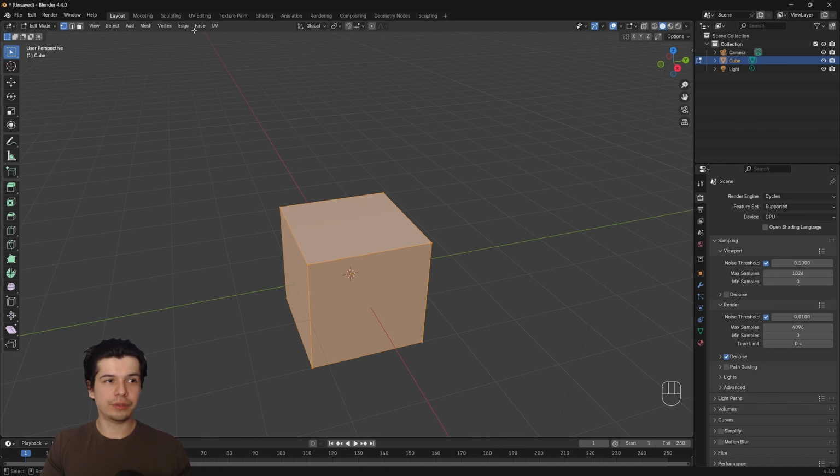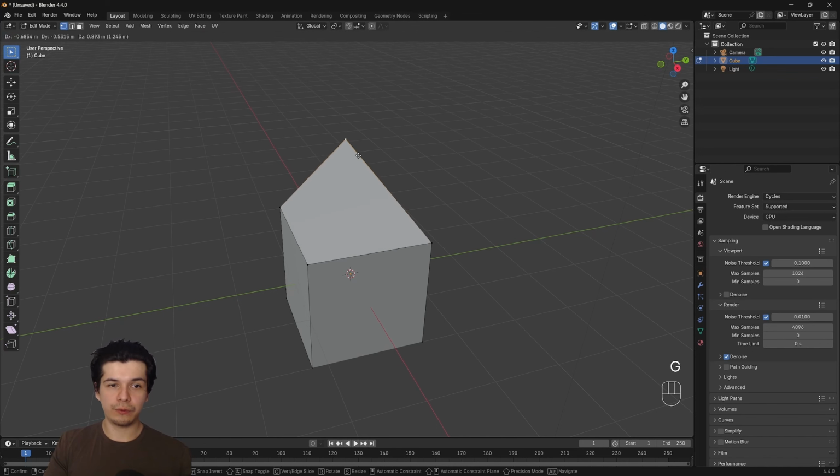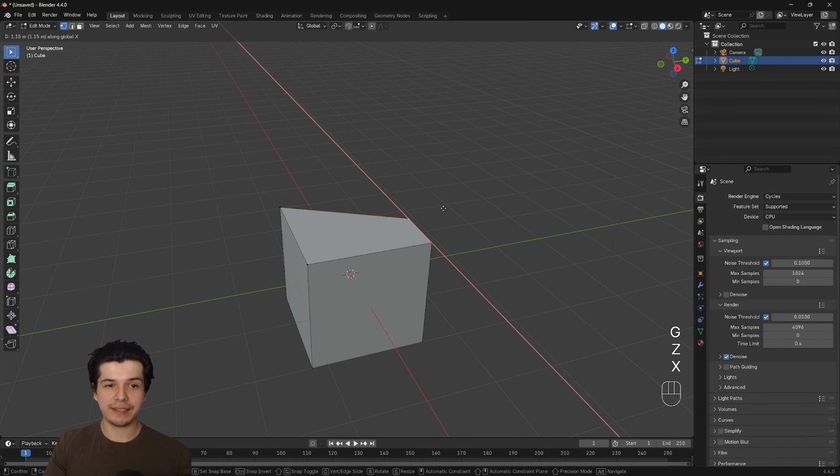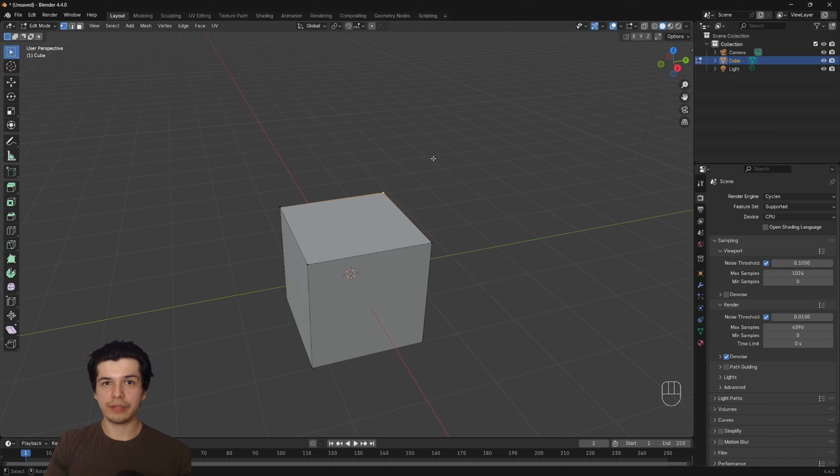If you go again to the left corner, we have 3 options to edit these. So the transformations we were using work here as well. It's the same principle. If I'm gonna press this mode and press G for move, I can move this, I can lock this in an axis, and I can write numbers. Right click to cancel the action.